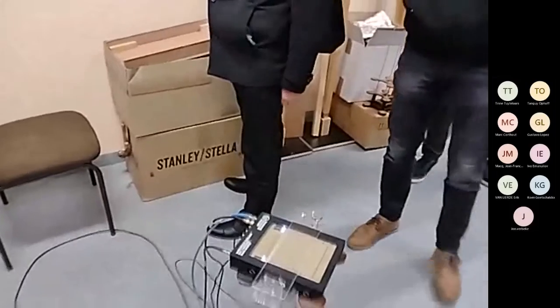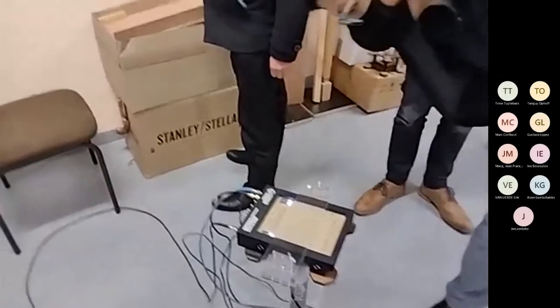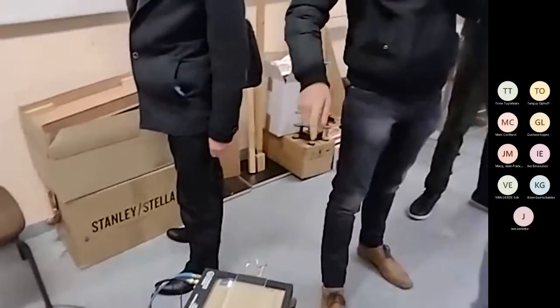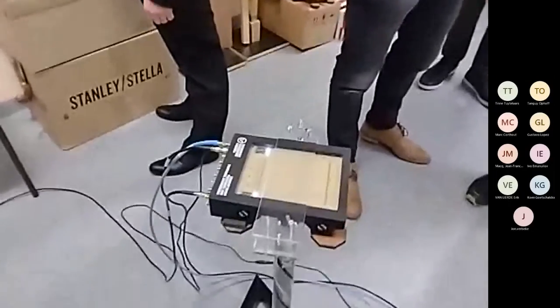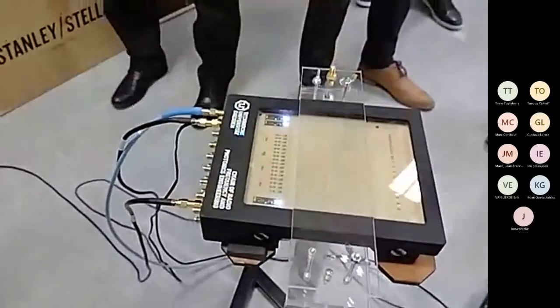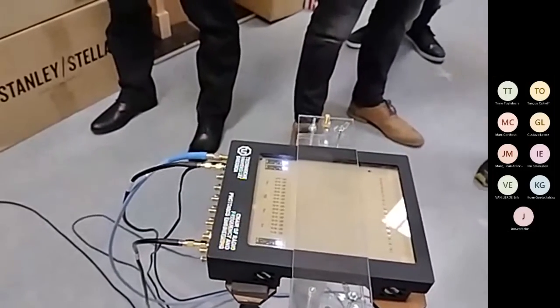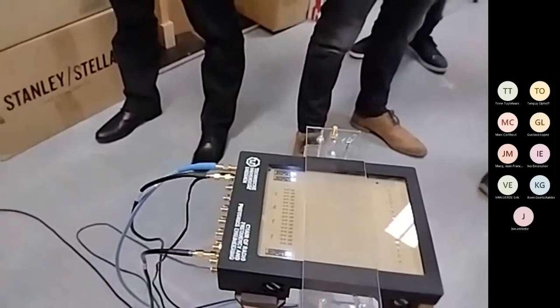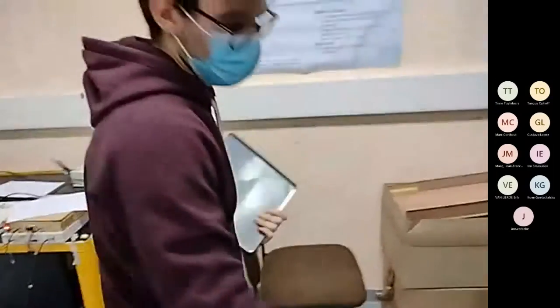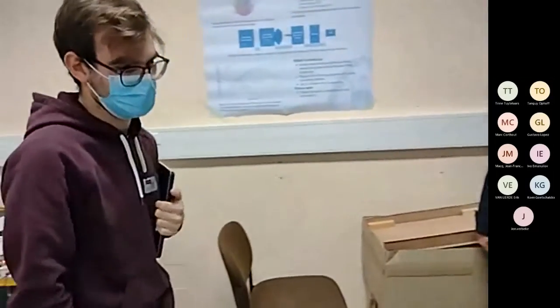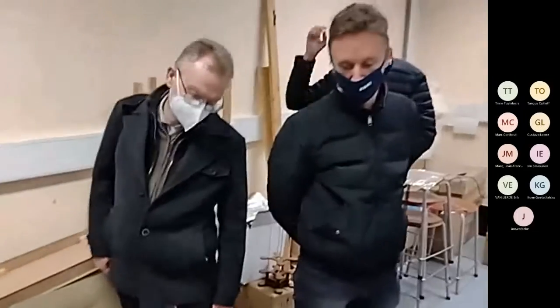So for millimeter wave, the antennas are a few millimeters. Normally these are just antennas in an array. If you want directed beams like here, you need to do phase shifting between the signals. So there, this RF circuitry comes into play. You basically use delay lines.